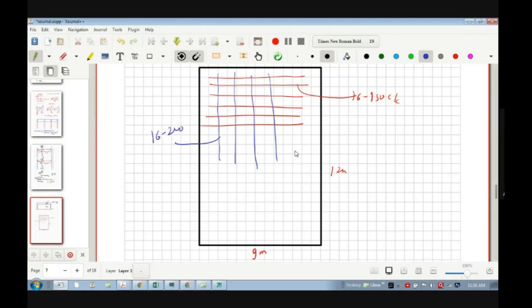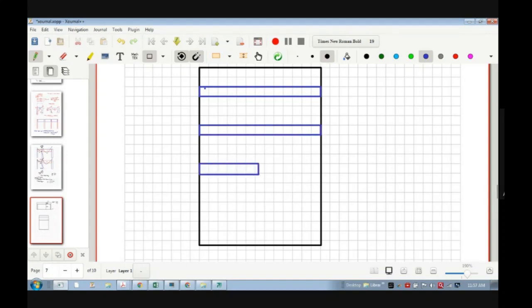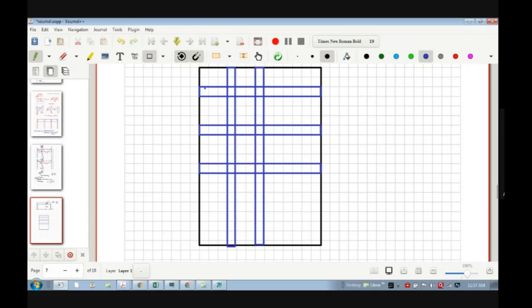But in our case, it is grid slab. So in that case, what happens? Whatever steel is here, we are concentrating that steel within the strips. What I'm doing, steel percentage is same, but I'm just putting concentrated steel. So in every beam, I'm putting the steel. यहाँ जो beam है ना मेरे grid. So I am putting that steel within each grid, and these beams are acting as, we can say, one-way direction of the slab, and this will have two other direction of the slab. So this is also one of the cases.